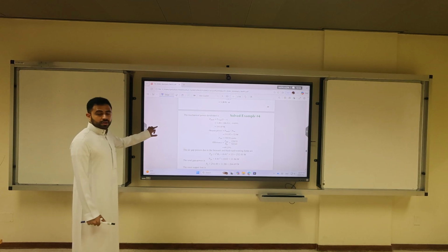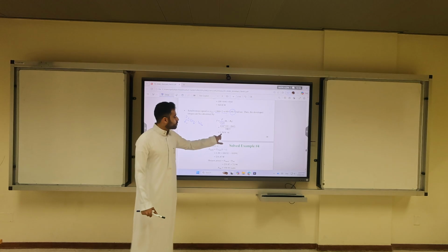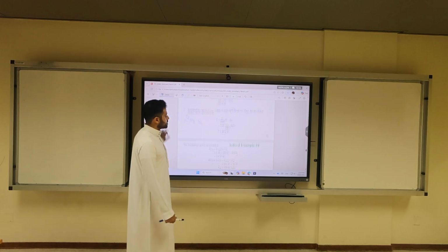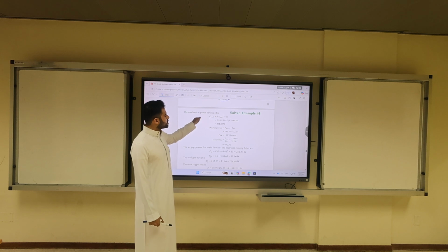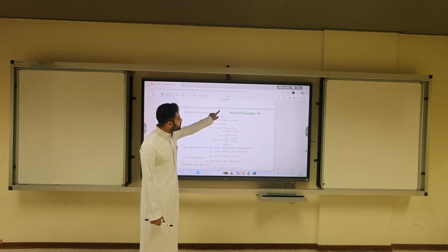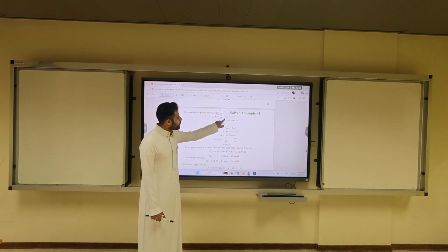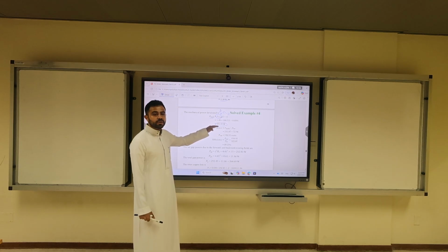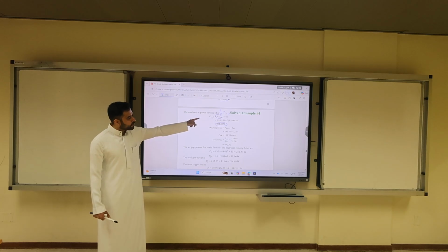Clear? So, let's talk about the mechanical torque. It's 1.28 Newton meter. That's a very small number. So the mechanical power is the air gap power, this is PG, times 1 minus S. If you multiply it by 1 minus S, you get 23.87. Maybe the mechanical power will be a little bit slightly higher. So this is the mechanical power.